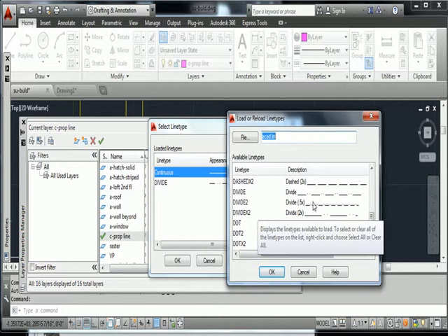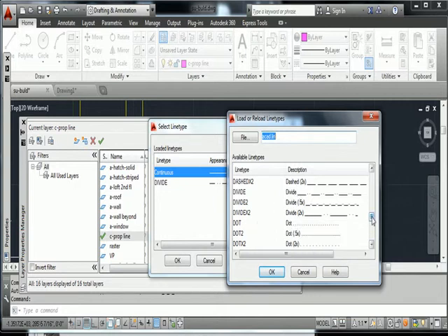Notice that the sample line that's there, it looks like the divide 2 is only like 0.5, only half the line length of the one that is the regular divide. And the divide x2 means that it's double the length. Okay, so if you're going to use a similar type of line type, but you want to scale them differently, one way is to use these preset